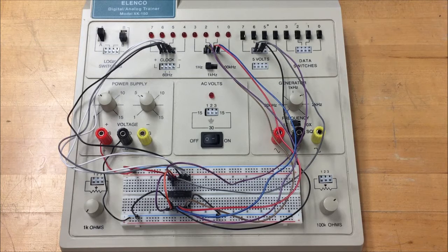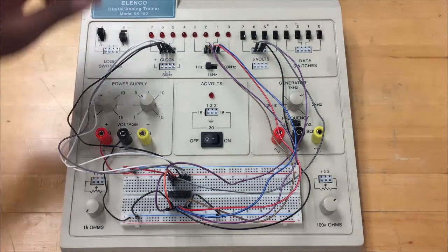Next, we will check the decoder IC. There are 3 inputs and 8 outputs. The decoder used here is an active low decoder. Here, the least significant bit A is connected to switch 7, B to 6, and C to 5. The outputs 2Y0 is connected to indicator 7, 2Y1 to 6, 2Y2 to 5, and so on.